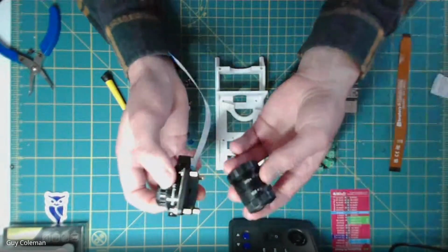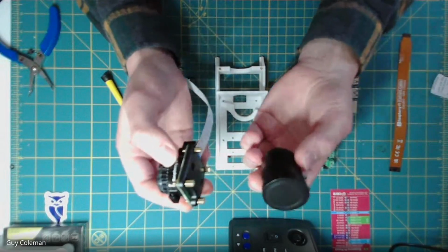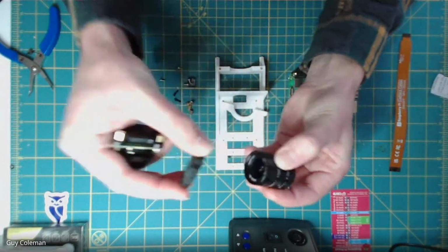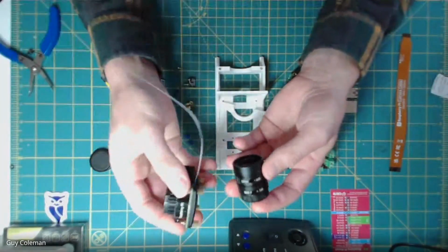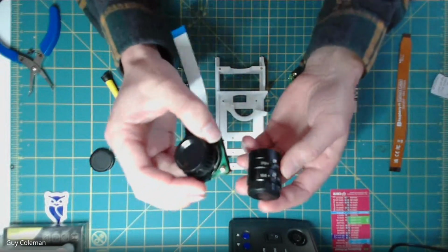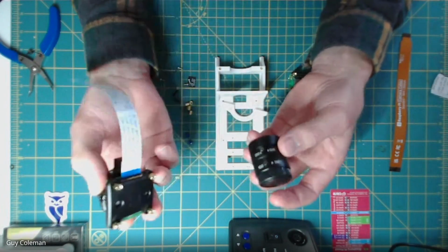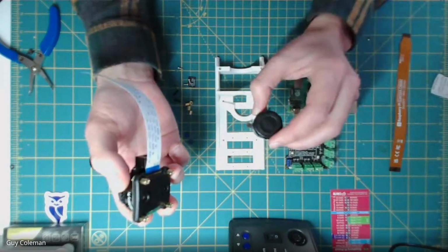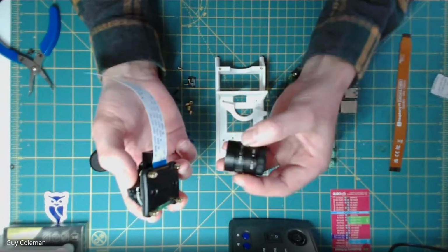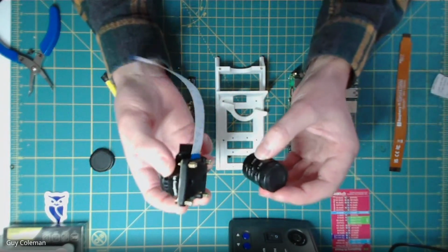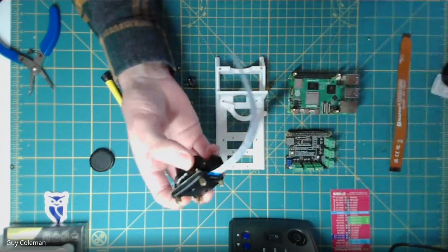We also use, or it's designed to work with, the 6mm CCTV lens from Raspberry Pi as well. That just gives us the right field of view when mounted at 1.2 meters above the ground. So 1 meter wide to run 4 25cm nozzles. But of course, you can change the lens over or change the mounting height depending on the situation.